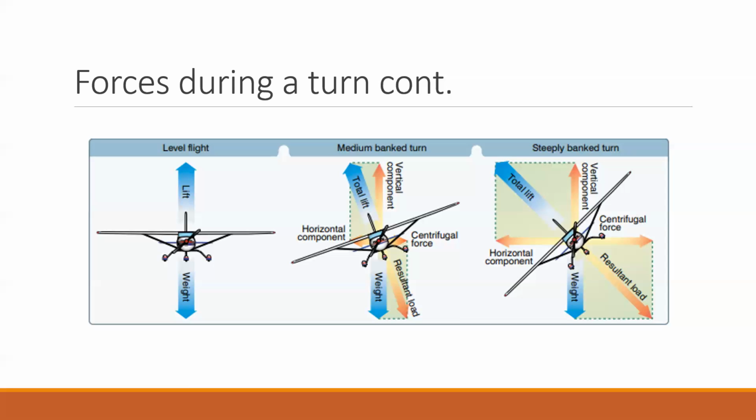and that's pointed perpendicular to the aircraft. Once you get into a steeper bank, your horizontal component will extend greater, and your centrifugal force will also increase. You can see that this total lift vector is pointed out at a 45-degree angle. If you were to exceed this, eventually your vertical component would get smaller than your horizontal component. But yeah, hopefully that makes sense.